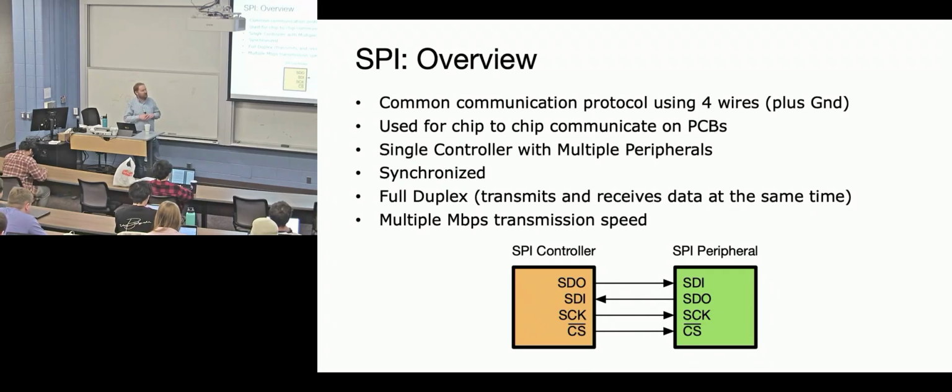One of the challenges, as you'll see for SPI, is there's not an IEEE standard for this. This is kind of like a methodology for communication that's kind of evolved over time, and things like clock polarity, bit polarity, timing, all those things have generally just been agreed on by manufacturers, and now it's kind of coalescing into a more well-defined spec, but it's not governed by anything. At least that's not how it started out.